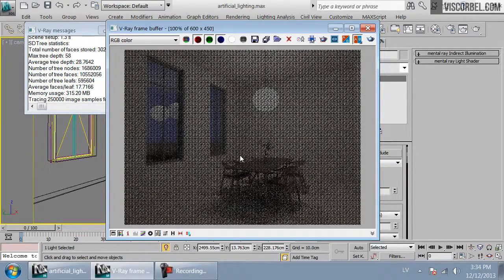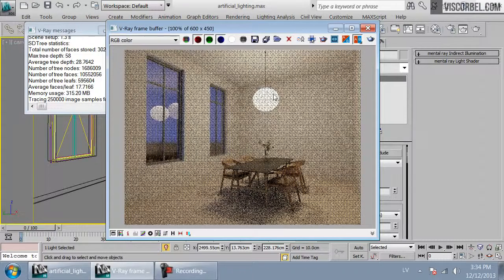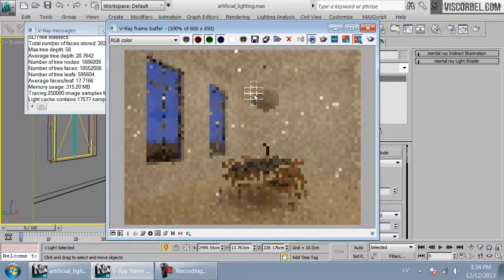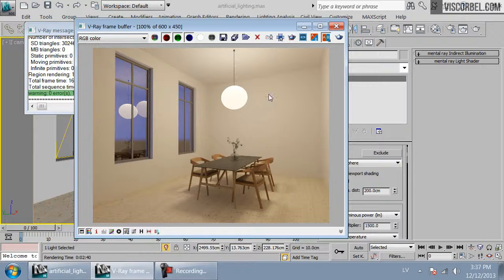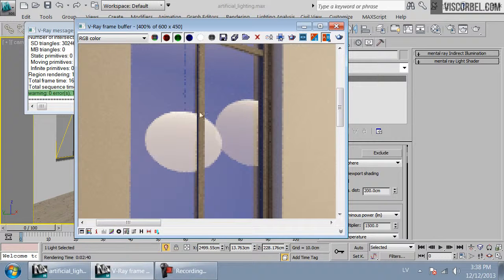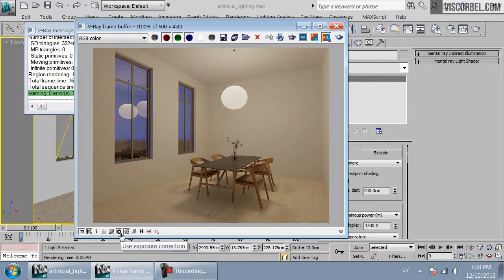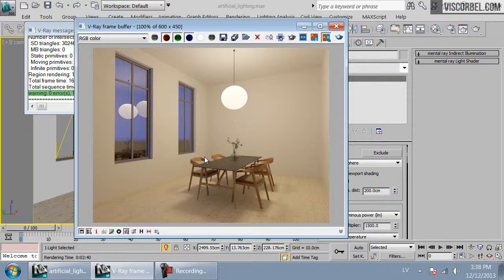And this usually renders faster than if you would light it using the single light source inside and refractive glass material for the lamp. As you can see, this area renders very quickly, since the vray two-sided material is pretty fast. And here's the render. You can see that it rendered very fast, and the light distribution looks okay in these dimmed reflections, and the light also looks quite good. You have this detail to recover if you're using some tone mapping. So this is a good way to speed up your renders and still get a realistic result.